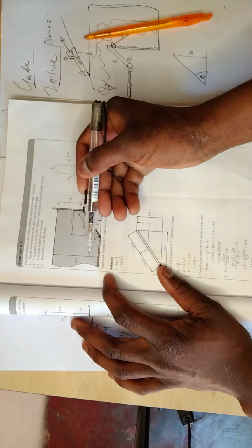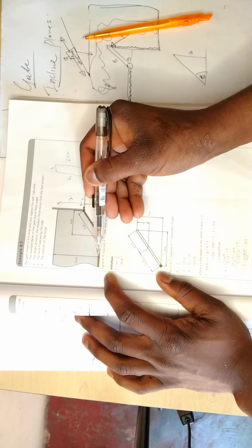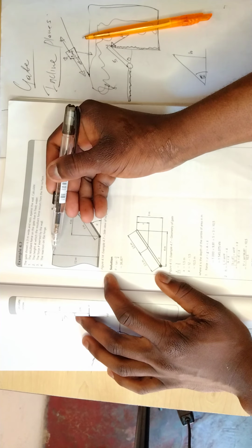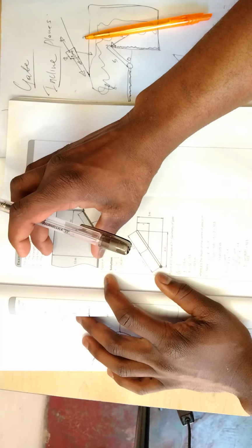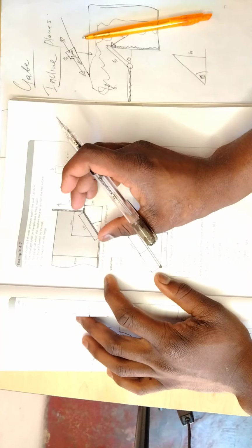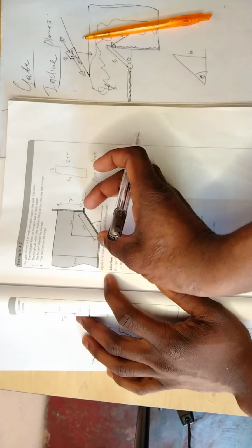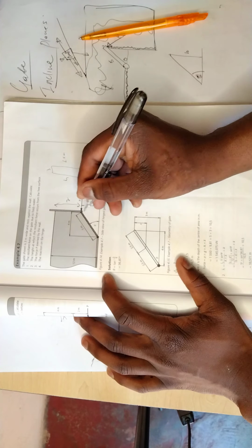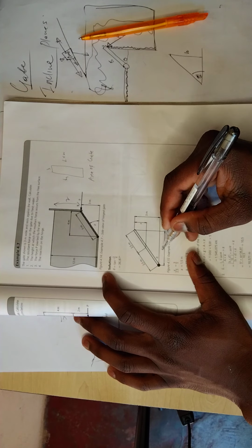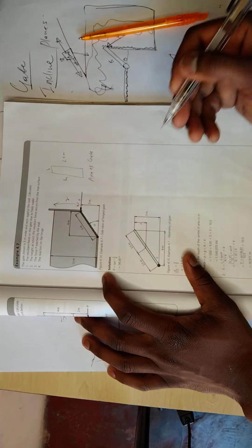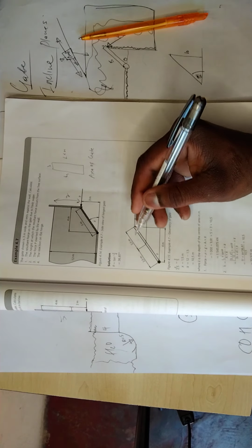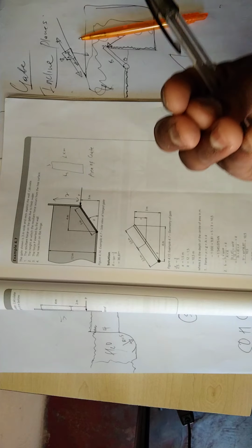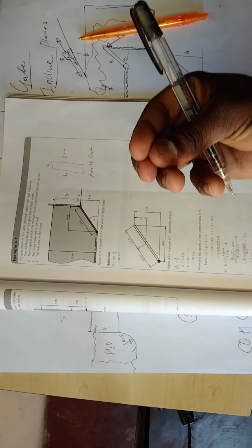So if we check, they say from the wall bottom to the surface of water is 12 meter. So we automatically have the height of our water. We come to the gate. Our gate is 5 and it's 3, and they say the position where it stays is 4. So automatically we can make a small triangle like I just showed you. You see here they've made a small triangle, they make 4, and here they break this into 2.5, 2.5, it's 5. Why are they doing this? They are doing this so that they can find the centroid.